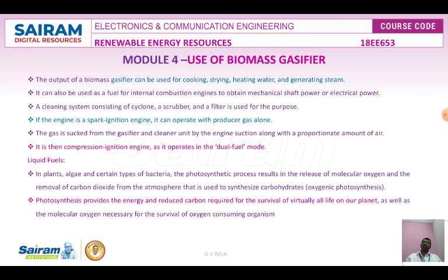The output of the biomass gasifier has a variety of thermal applications: by using that biomass we can go for cooking, drying materials or products, heating water, and generation of electricity with the help of steam. Sometimes the biomass gas is also used as a fuel for internal combustion engines in order to obtain mechanical shaft power or electrical power. If it is used as a fuel in an internal combustion engine, it has to be cleaned first properly by removing particulate material like tar.